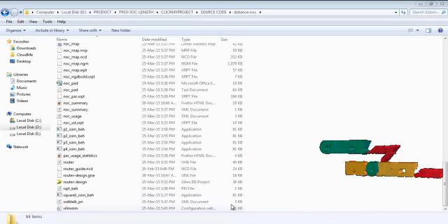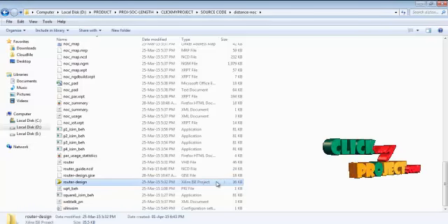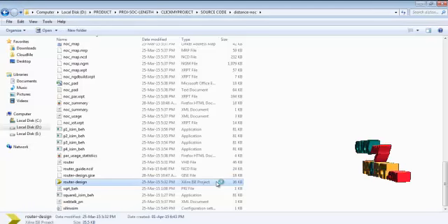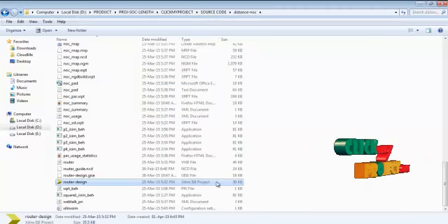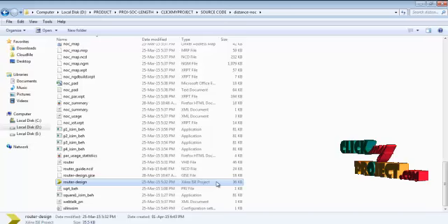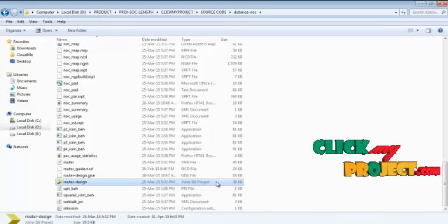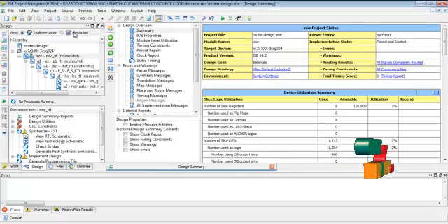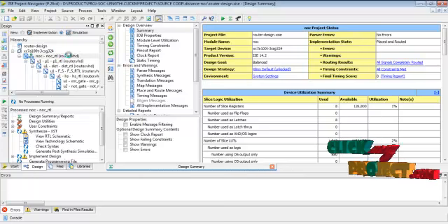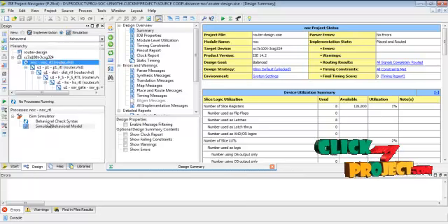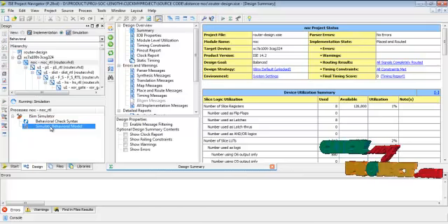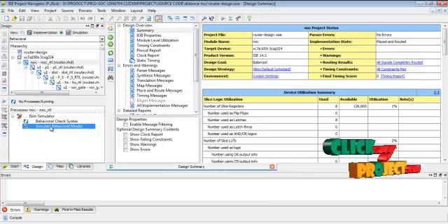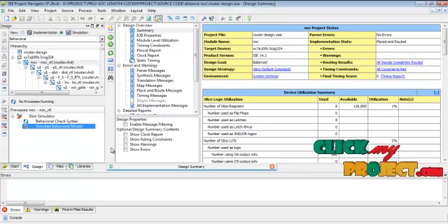Next, we see the final output for the product. First, we design the Xilinx ISE project for router architecture designs. Then we open the router designs, which were developed in the VHDL language, using the structural modeling process for the overall architecture designs. Next, we select the simulation process, and select the NOC design to run the simulate behavioral model. Then we open the ISim process level, which is used to simulate the overall NOC architecture designs based on the wire length minimization methodology.